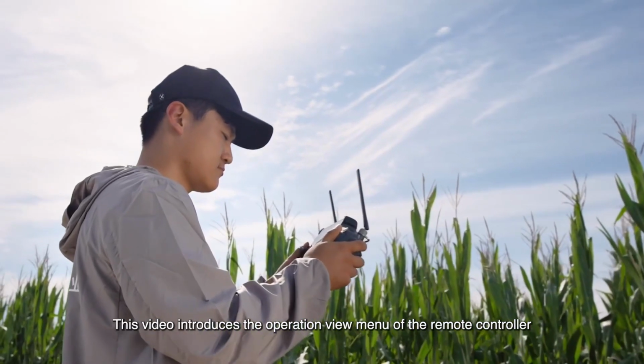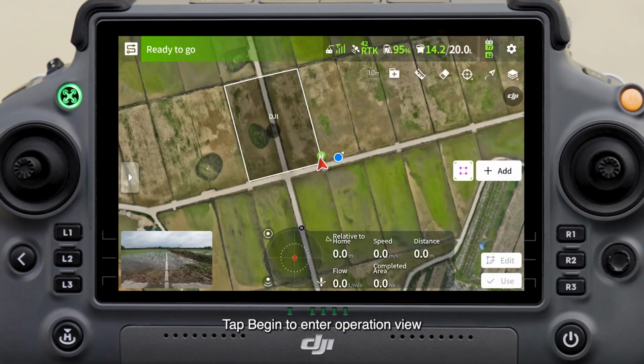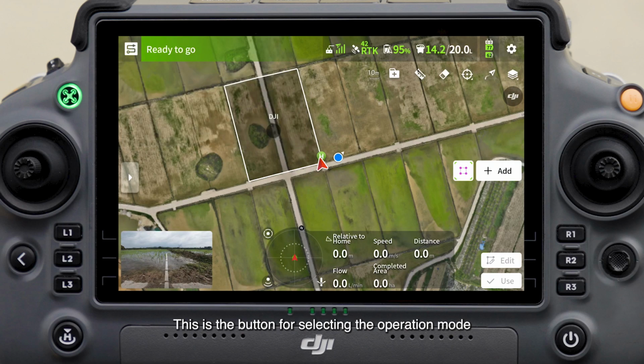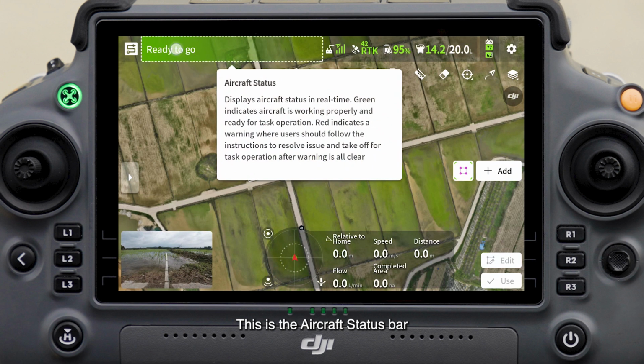This video introduces the Operation View menu of the remote controller. Tap Begin to enter Operation View. This is the button for selecting the operation mode, which can be route, manual, fruit tree, route mapping, and fruit tree mapping. This is the aircraft status bar, displayed in green when all systems are working properly, in yellow when